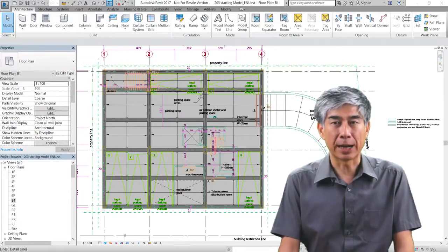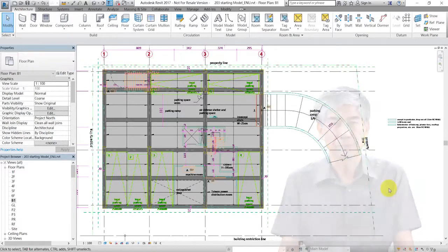We can identify in the underlay that there are two types of walls in B1F. The walls around both shaft and elevator are brick walls, and others are RC walls. Let me show you how to construct the top row of the walls as a demonstration for wall modeling. You can follow the same procedure to finish the remaining walls by yourself.